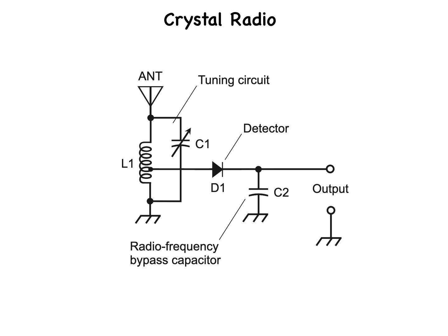You can't call this circuit complicated by any stretch of your imagination, but it performs some sophisticated tricks nevertheless. Aside from the antenna, an external component such as a wire running out your window to a tree, and a sensitive earphone or headphone that you can connect at the output terminals in order to hear radio stations, however faintly, this circuit contains only 4 components: the coil, the diode, and 2 capacitors.